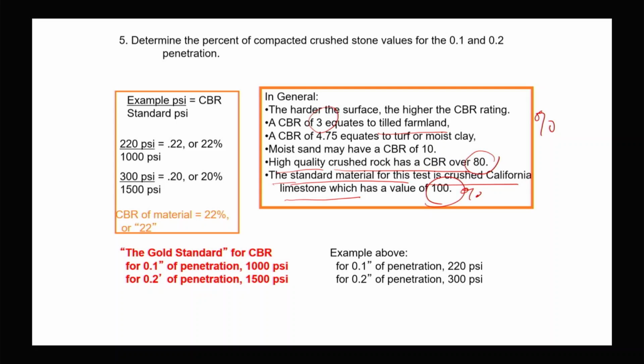So we use our geotextile depending on the CBR value, and we also select the stiffness of the geotextile based on the CBR value. Where the CBR value is low, to enhance the strength of the system we need a stiffer geotextile. Stiffness should be high.